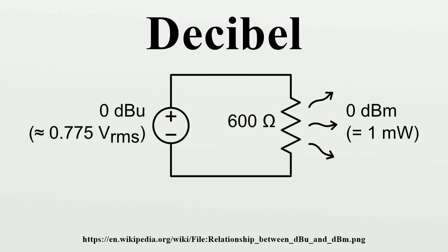Advantages and disadvantages. Supporting arguments. According to Michka, the advantage of using a logarithmic measure is that in a transmission chain, there are many elements concatenated, and each has its own gain or attenuation. To obtain the total, addition of decibel values is much more convenient than multiplication of the individual factors. The human perception of the intensity of sound and light approximates the logarithm of intensity rather than a linear relationship, making the dB scale a useful measure.